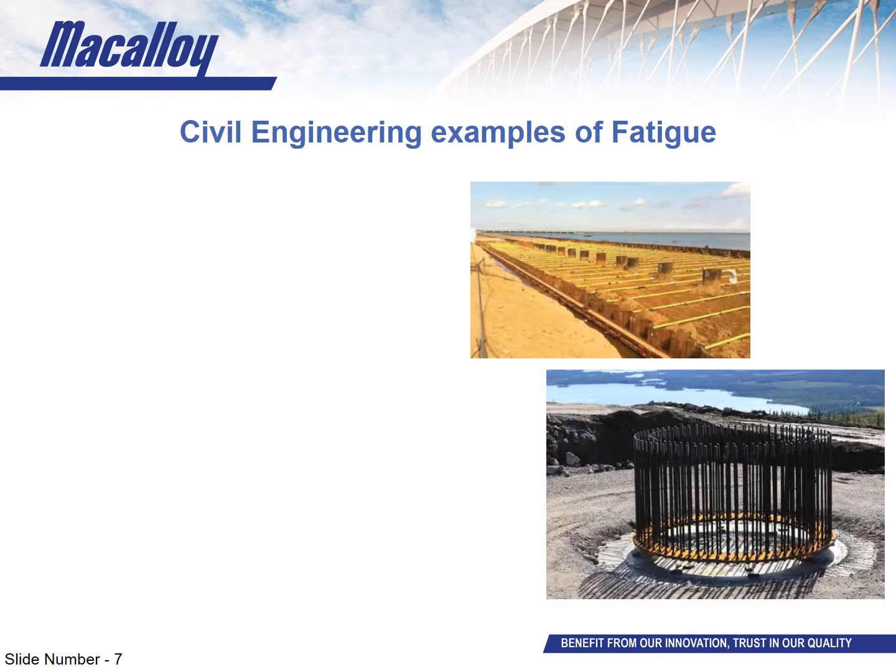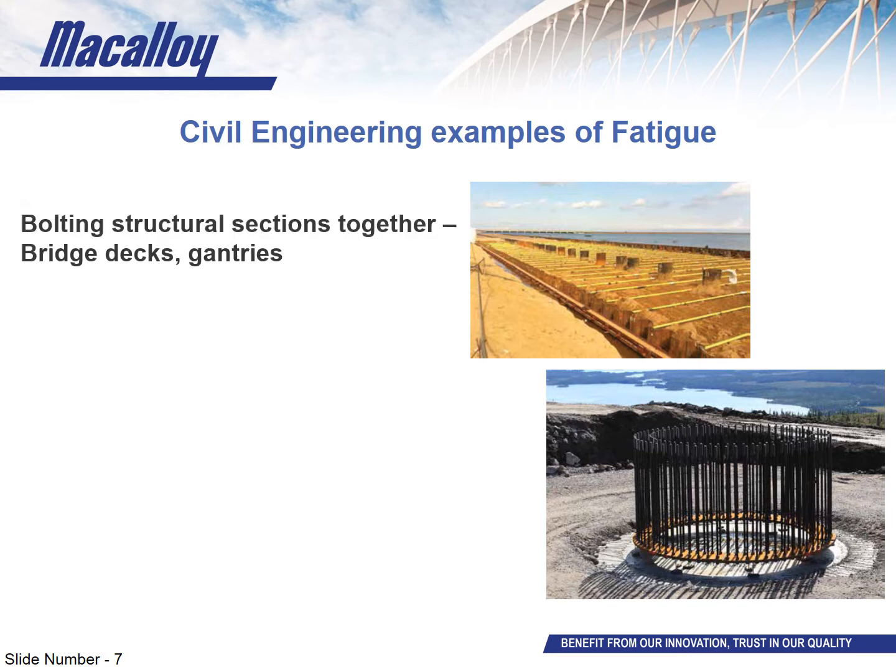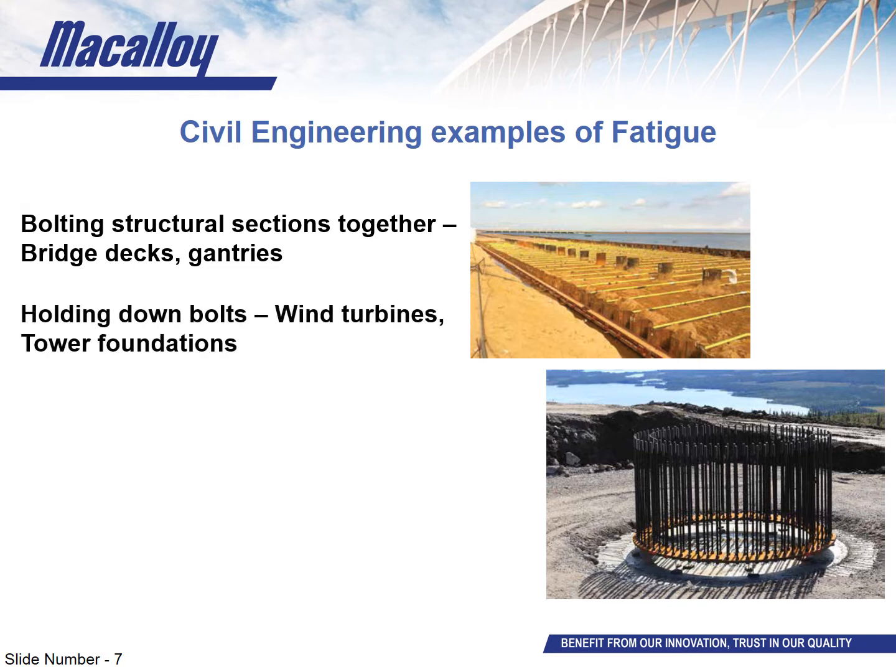By no means is this an exhaustive list, but these are a few examples of applications that can experience fatigue. Now this is to give you an idea of the application so you can relate to it when we're discussing more detailed points later on. Structural sections that are bolted together using steel bars such as bridge decks or maybe gantries can be subjected to oscillating loads as the structure is loaded and the sections move relative to one another. Holding down bolts are a product with widespread applications and can vary from wind turbines to flood defense anchorages and many more. Often the devices or structures that they are holding down are subject to a plethora of loading types that are repetitive and therefore cyclic.